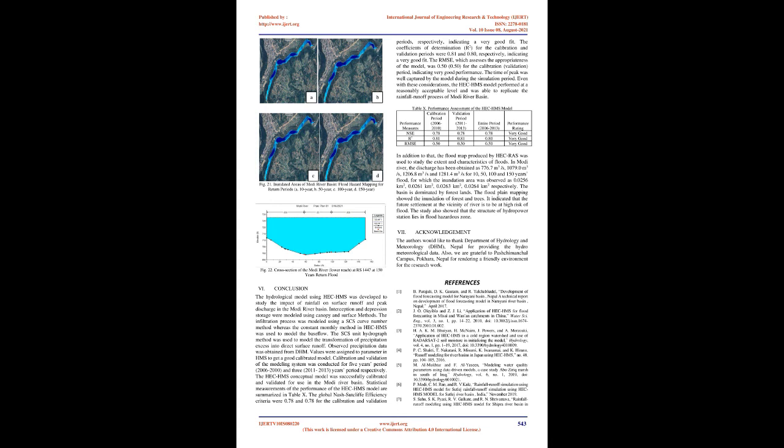The flow values from Modi River Station 406.5 were used to calculate the flood values for different return periods. The flow value was obtained from the Gumbel distribution method. The inundation map of Modi River due to 10, 50, 100, and 150-year return floods is shown in Fig 21. The dark blue color shows the greater depth in Fig 21 and light blue color shows the reduced depth.